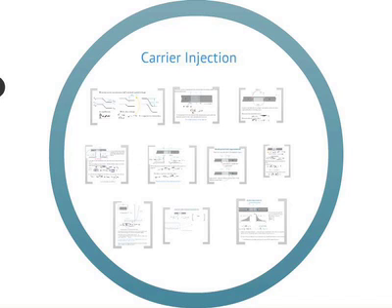But what happens is essentially you have the holes, the majority carriers here. Once they diffuse across, they become minority carriers, they diffuse and they combine. That process is called carrier injection. They're essentially injecting the majority carriers from one side to the other side, where they become minority carriers. Okay? That's the carrier injection that happens under forward bias.